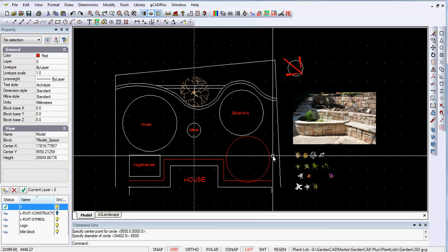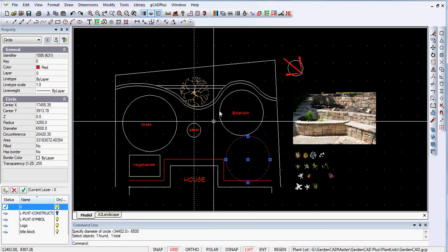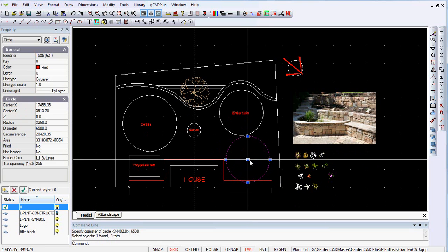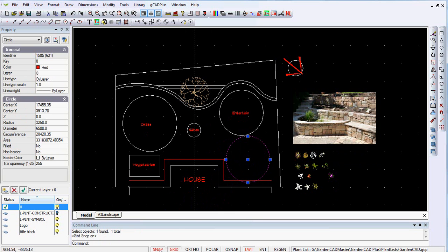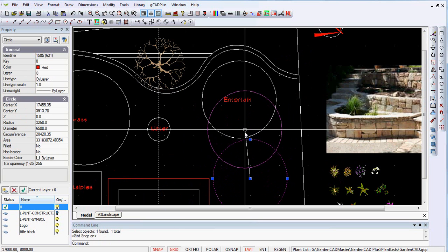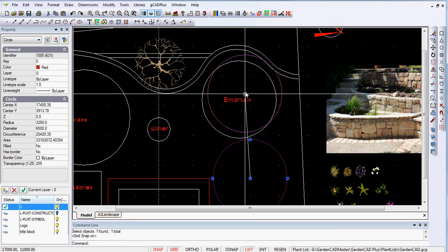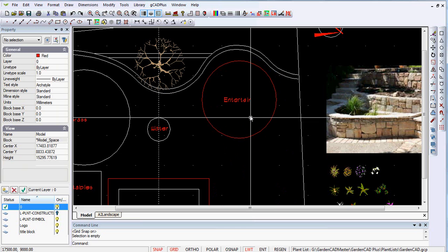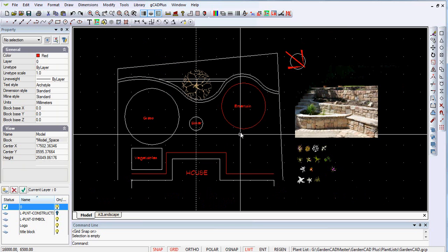And there's a circle. What I now want to do is to position it accurately on the grid. I can do that by clicking in the center of the circle, then coming down to the snap option here. As I move around, I hope you can see that it's going click, click, click, click, and it's locking into the grid, so I can put it down there. So now the red circle sits in the correct position.